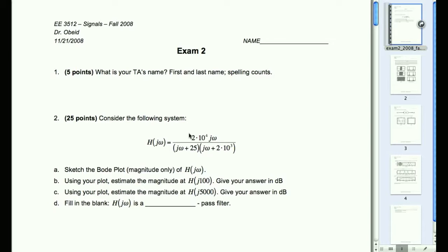If you think about a j omega filter, if you're just multiplying by j omega, that means low frequencies, where omega is small, are being multiplied by a small number. And when omega is big, that's a very big number. So by default, j omega is a high-pass filter. And it makes sense, because j omega takes a derivative.